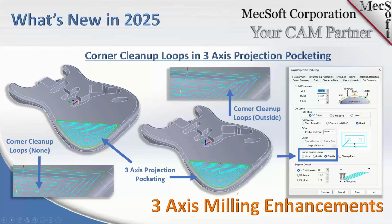More importantly, if the corner is really steep, you could actually end up leaving material there because the tool is turning very dramatically, and so these cleanup loops will go in and clean those material stubs that are sitting on the part. As you can see up here in the corner cleanup loop, I have it set to outside.